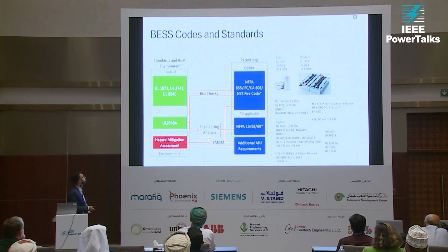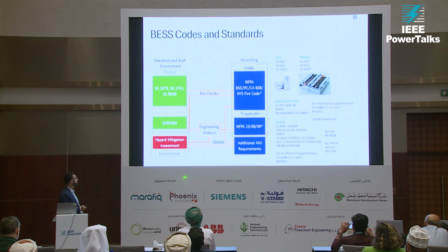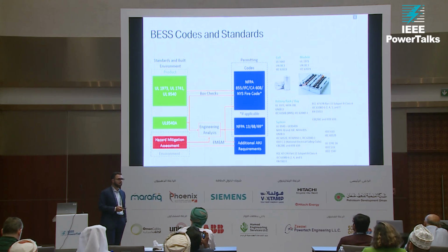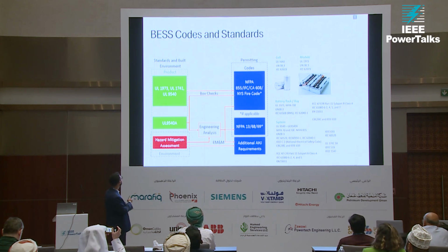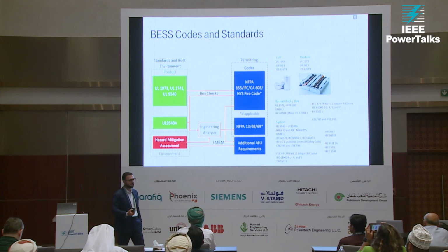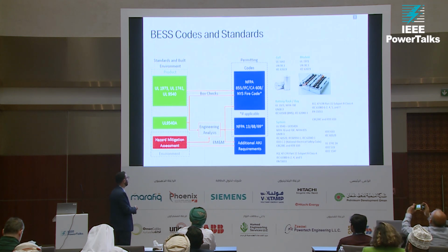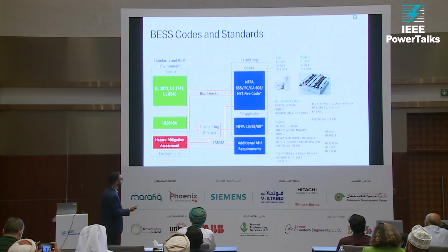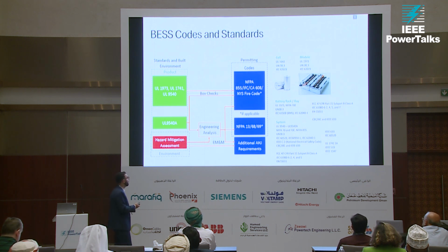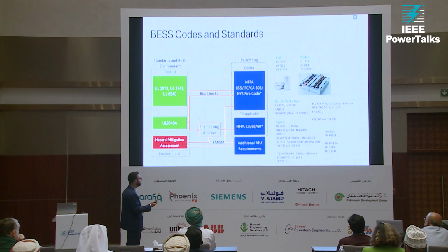Okay. So let's talk about codes and standards. I remember when I started working in energy storage systems about 12 years ago, we did not have a single standard for battery storage systems. The only standard we had was UL 1973, and that's coming from your cell phone testing requirement. That was pretty much the only standard out there. Since then, the industry has evolved to include a lot of standards. Some of them are international, like UL, IEC, IEEE, UN as well. A lot of them are international, but there are some local standards like NFPA.